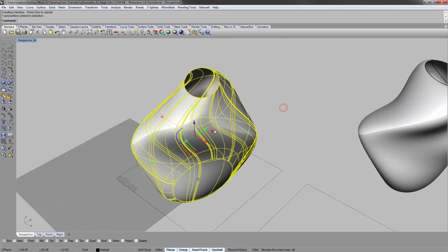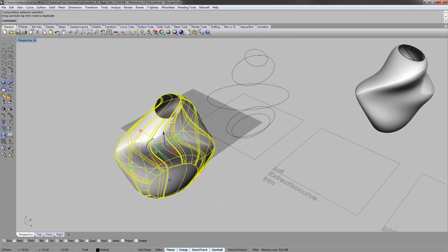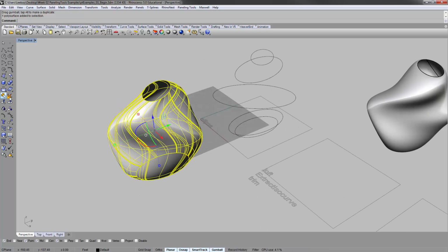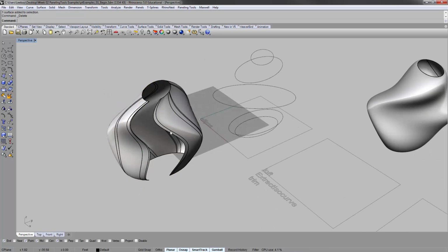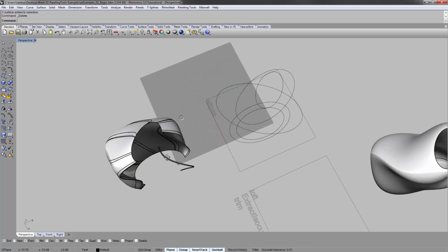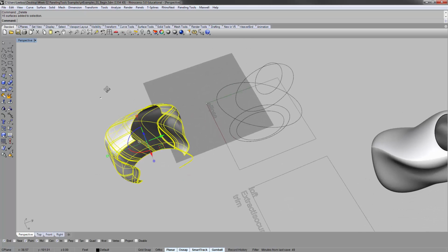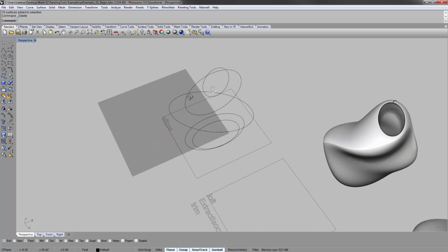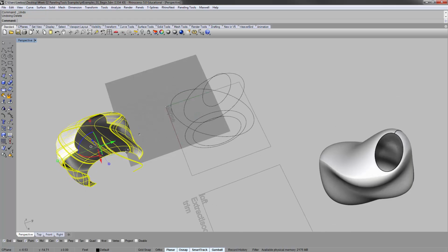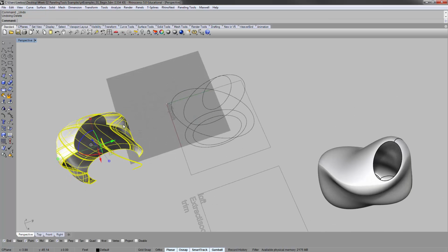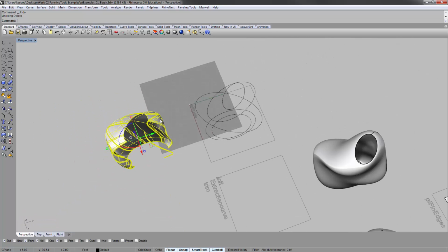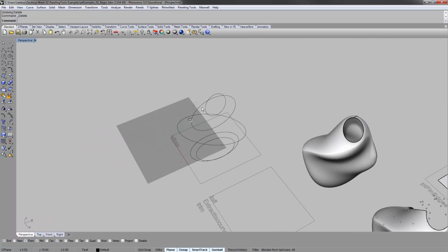If they are not aligned, the result that you get is something like this, right? A very crazy, and if I explode it, very fragmented polysurface, which is not what we want at all for something that is going to rely on surface subdivision, because in this case you would have like 20 different surfaces to deal with, all with different widths, addresses, etc. So that's not desirable at all.